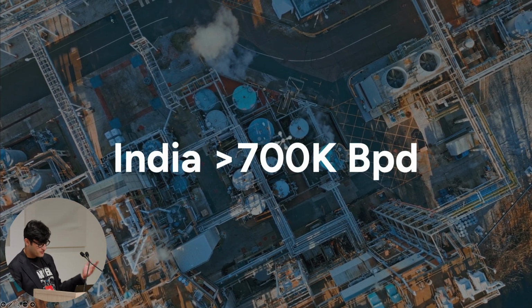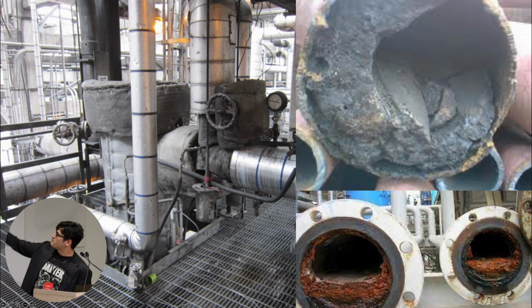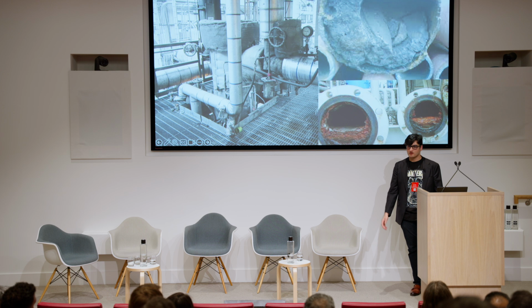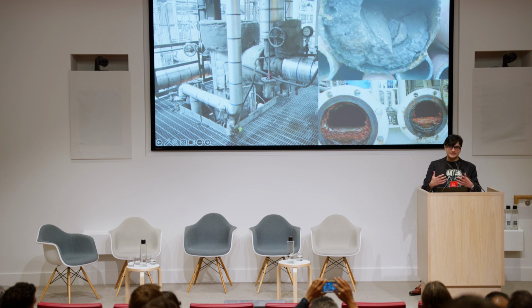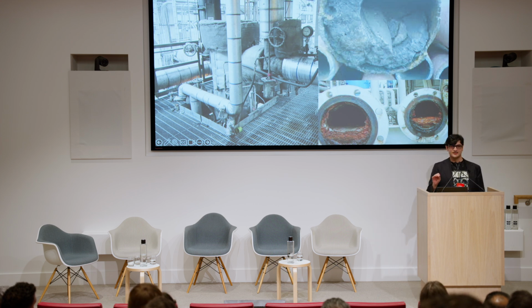So take a good look at this picture. Right. That thick black crust, or in this case a little bit brown here, that thick black crust is known as coke buildup. It forms when the actual contents within these pipes, i.e. hydrocarbons, don't fully combust. It's like cholesterol in arteries. It really chokes the flow, right? And once it starts, the heat transfer fails, pressure drops, equipment strain, but the worst of all is the entire unit has to be shut down to clean this out.